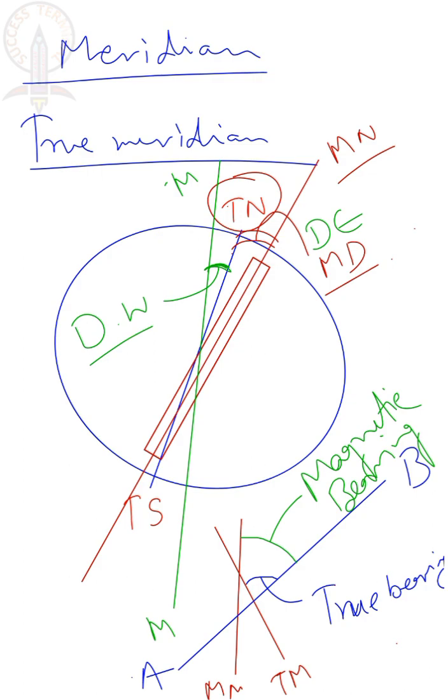And this magnetic declination is not fixed for a particular place. It behaves like a pendulum. At a specific place where the declination is right now 5 degree east, after 100 years or say 200 years, you may find that the declination becomes maybe 10 degree west.